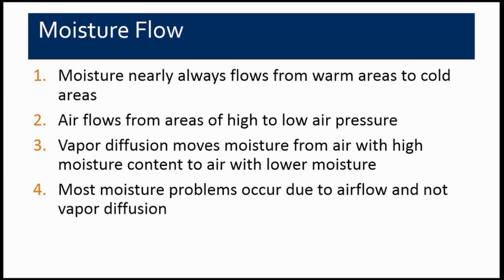A couple things to keep in mind is that moisture almost always flows from warm areas to cold areas. If you're involved in a condensation problem and you're thinking it's moisture within the walls that are cold that is causing the condensation problem, that's probably not correct, because the moisture has to be deposited on the surface. The air adjacent to the surface actually has to have more moisture than the surface that it's deposited on.